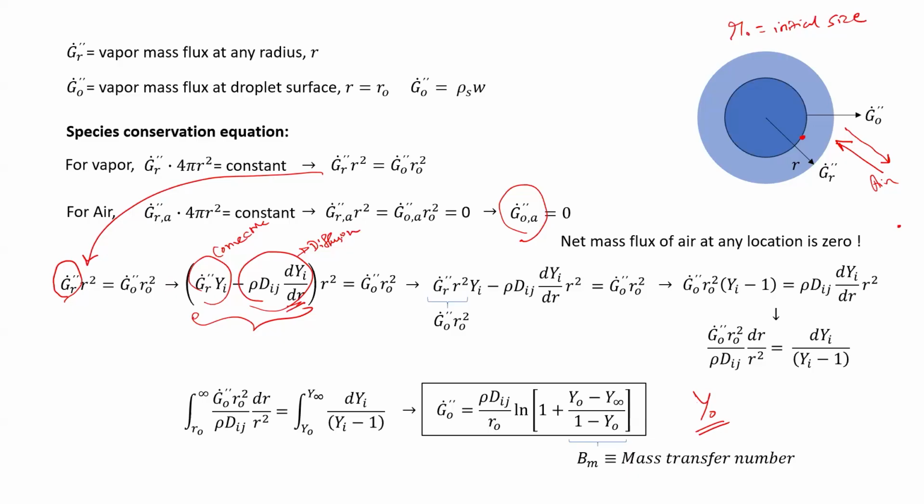By invoking Clausius-Clapeyron equation from thermodynamics. Okay. So, from there we can get the mole fraction, and from there we get the mass fraction. Okay. However, for this you need to know what is the droplet temperature, then only you can find out the vapor mass fraction by that way.